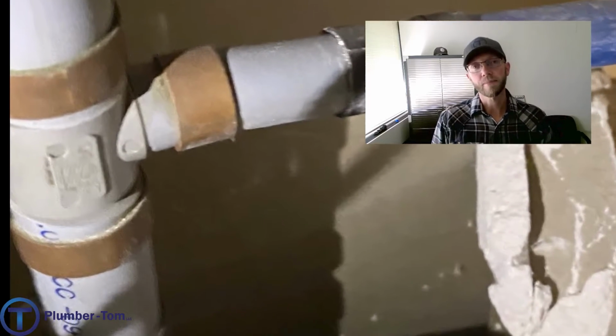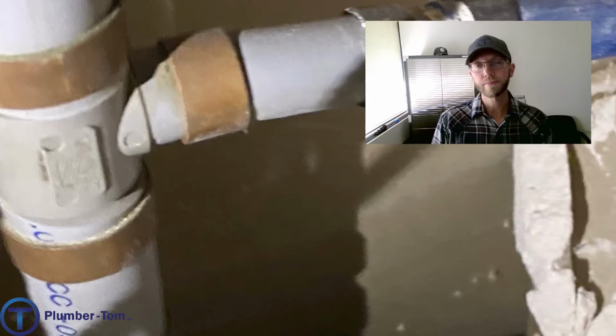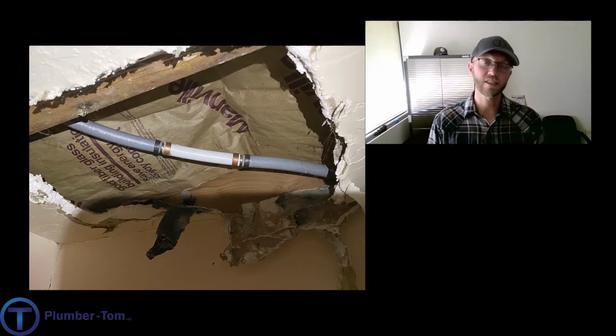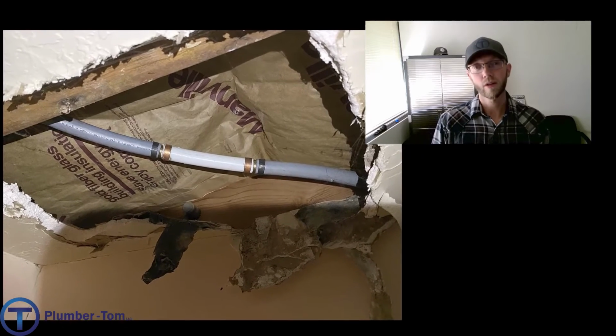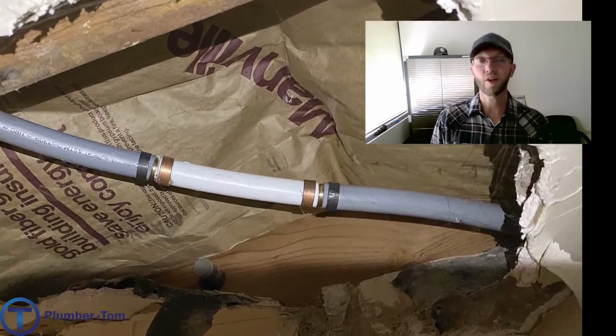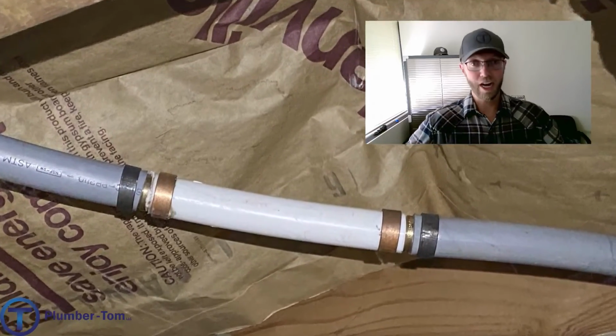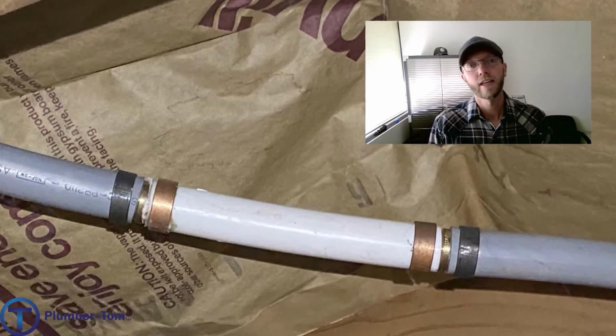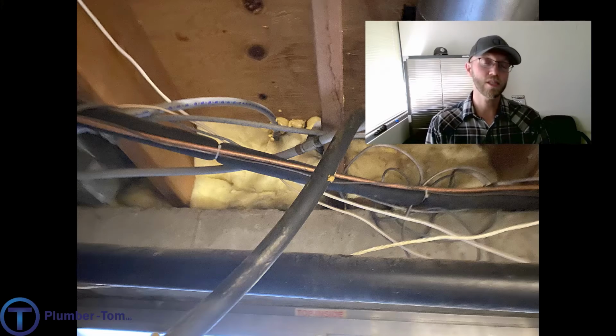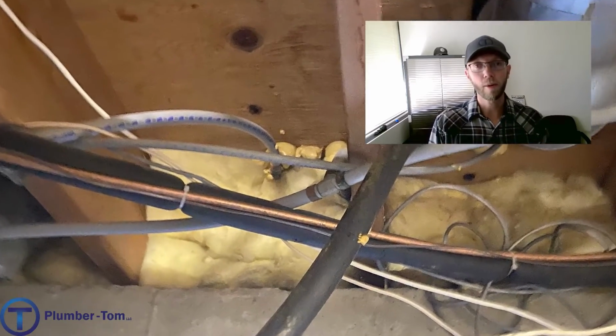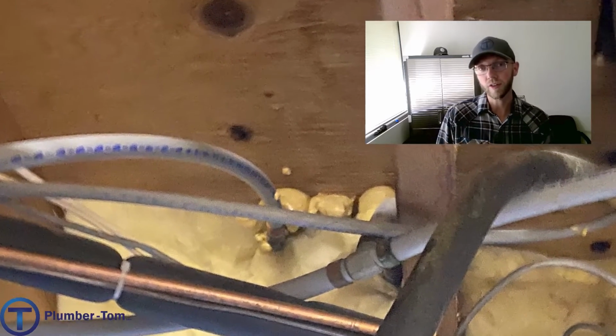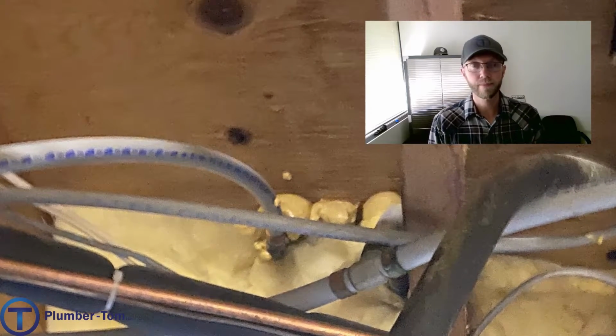But the problem was that the pipe itself was not very durable, and within a decade, there were so many flooded houses that there was an actual recall nationwide on polybutylene, and they said, yeah, stop the train, we can't install this ever again. And we haven't since. But there are still very many houses today that have polybutylene piping installed as their water distribution system. And they're just a ticking time bomb. You know, at any moment they could just flood the house.